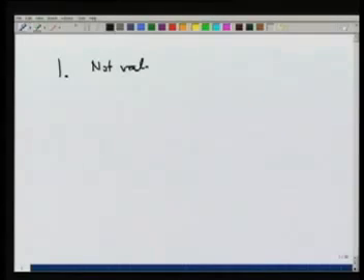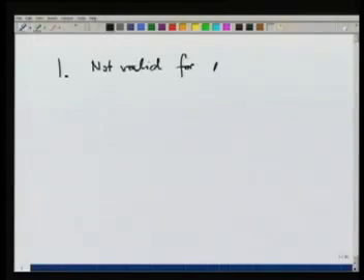The first limitation is that the unit hydrograph approach is not valid for very large areas. And when we say large areas, typically areas more than 5,000 square kilometers, the unit hydrograph approach will not be valid, because a lot of assumptions which we make in the UH analysis, for example, uniform rainfall over the entire area, will not typically be valid for a very large area. So typically we will say that the upper limit of applying the unit hydrograph would be about 5,000 square kilometers.